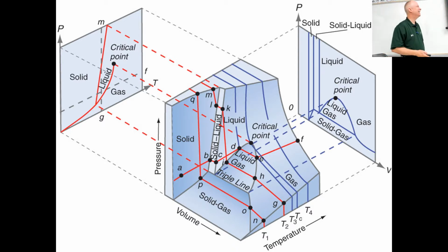Yeah, that's right. Okay, so then Jerome, what's going from C to D? So C, you're increasing temperature, your volume's changing very slightly too. Yeah. And the pressure's the same. Pressure's the same, yeah. Temperature's increasing. We're just heating up the liquid. Now you approach the liquid gas. Yeah, so it's expanded a little bit because again the liquid will expand when you heat it. And all right, and then Shini, what's going from D to E?